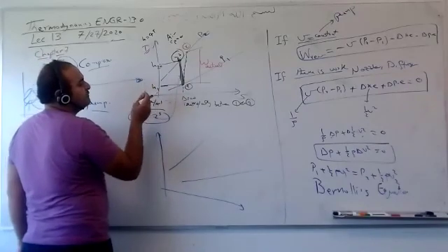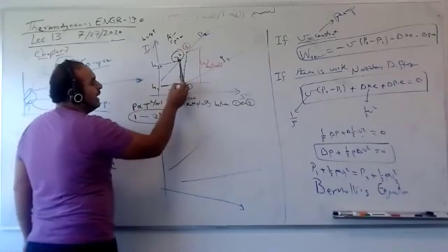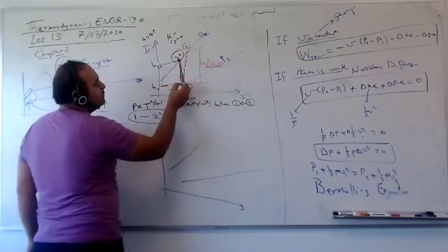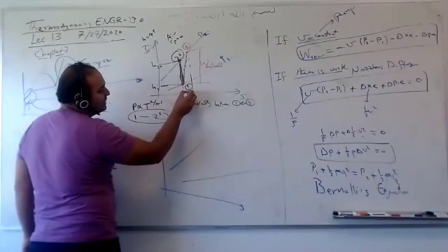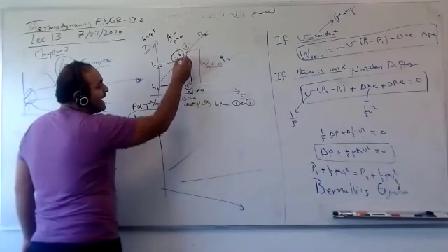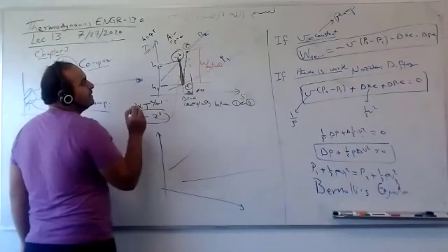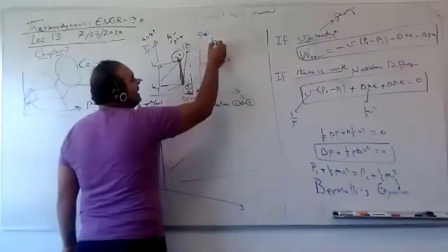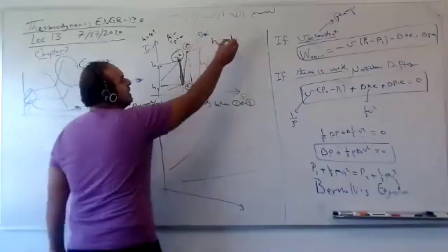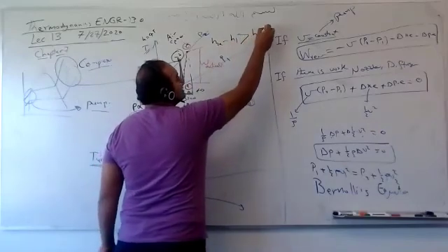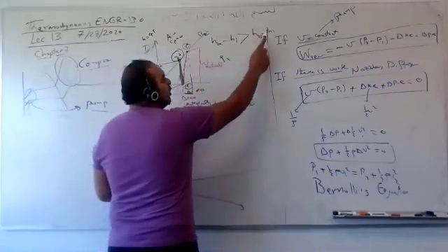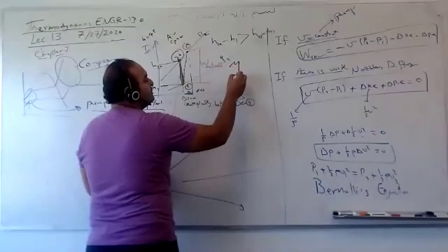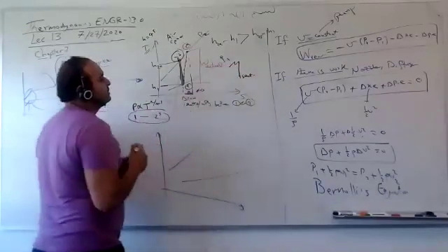But unfortunately, because of friction losses in the system, I go a little bit slanted, with more delta S, which is not equal to 0. This is actual, sometimes we use A. So I pay h2A minus h1. h2A is greater than h2S, of course. I pay more work. This ratio, the small over the big, we call isentropic efficiency. We're going to discuss it next lecture.